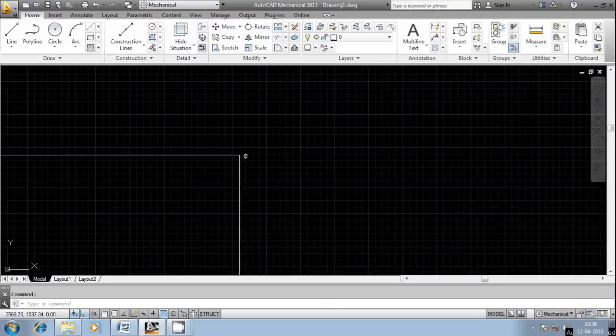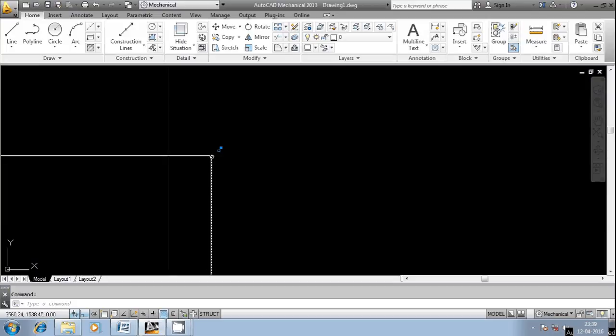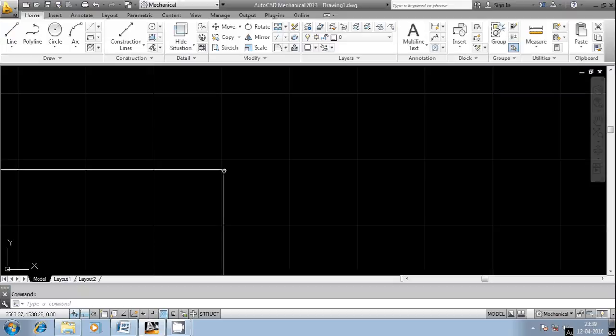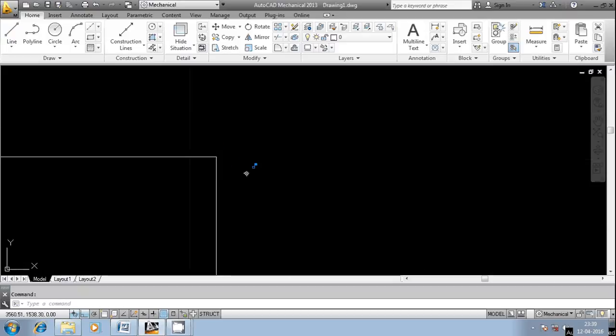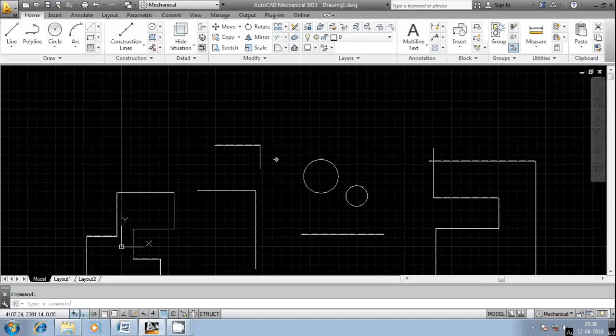Another important aspect is the safety of the operator. These sharp edges may cut the operator's hands. So that's the reason, from a safety point of view, we're going to round off the sharp corners or the edges. These are the two uses of fillets.